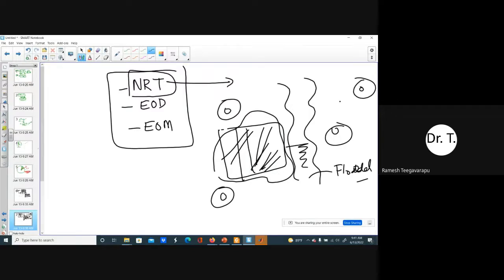at the end of the day, the vendor collects all the rain gauge data, checks for consistencies, checks for any problems, checks for anomalies, checks for physical values, checks for reference gauge values, and so on. It does all kinds of anomaly detections and outlier detections. And then they eliminate some of the rain gauges. For example, in this case, if we are using 200 rain gauges here, maybe we are only using 150 rain gauges in that region to develop what we call end of the day, and then probably only 120 very reliable gauges for end of the month. So these are the 3 products which can be used.